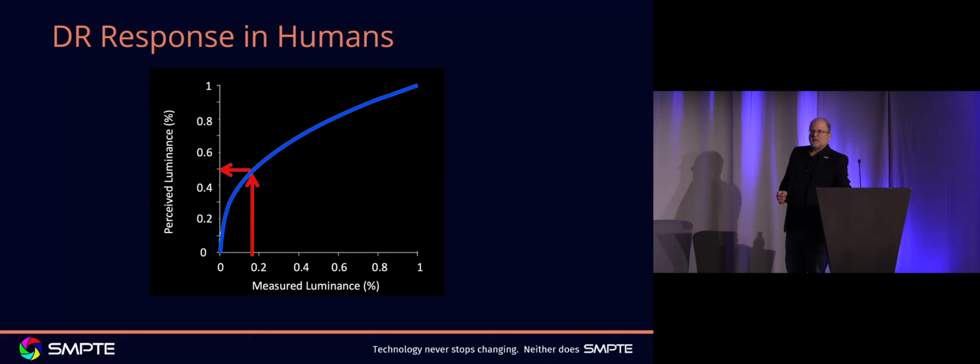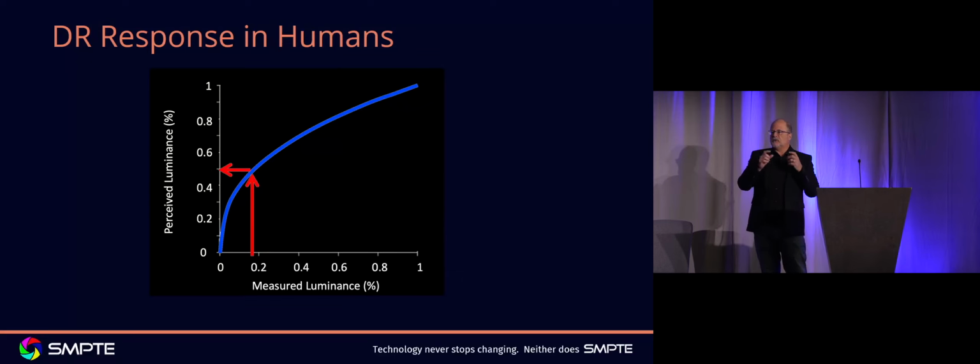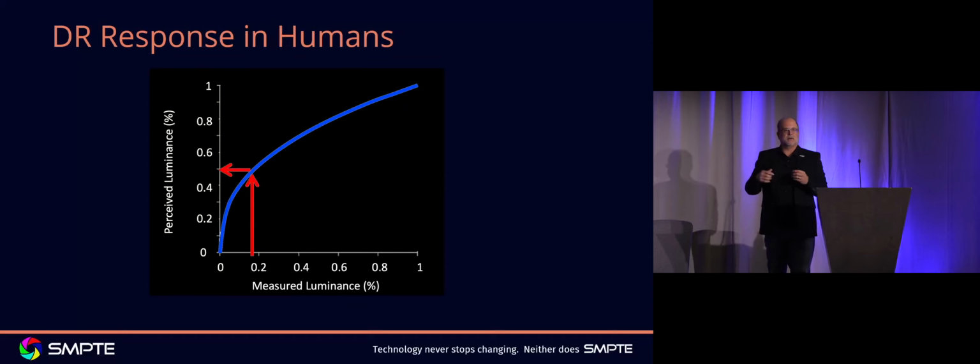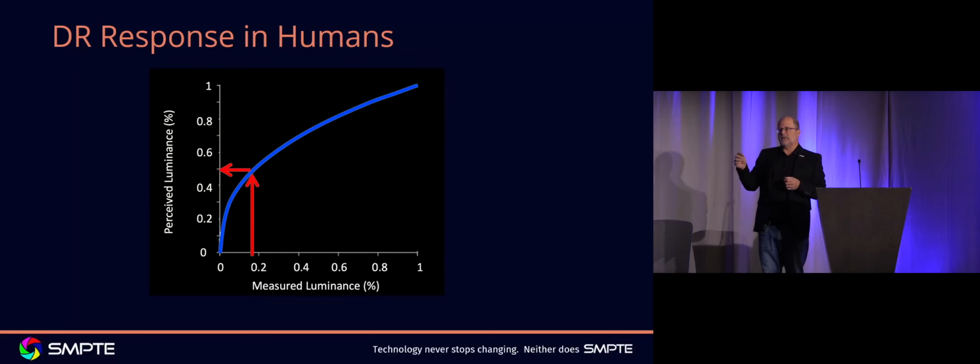So both use ST2084 as their transfer function. Just a couple of words on the transfer function itself. It was developed by Dolby. And the reason, like we said before, is that we have more code values used for darker areas than we have for highlights, which corresponds to the way we actually see the world. So it allows them to compress the whole dynamic range very faithfully and give you something from 0 to 10,000 nit range without apparent visible banding in 12-bit and very limited banding in 10-bit. So it's a very powerful transfer function.